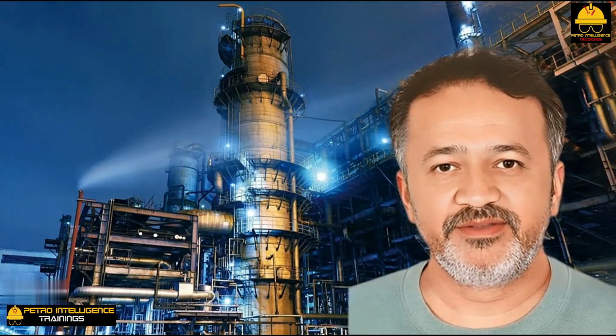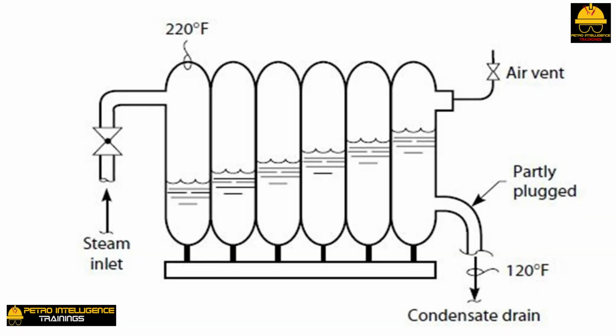Mechanics of subcooling. As the condensed steam flow out of the radiator is restricted, the surface area of the radiator available to cool the hot water increases. Hence, the water temperature leaving the radiator decreases. To summarize, the effect of restricting the condensate flow from a radiator or condenser is to build the water level in the radiator, reduce the rate of latent heat transfer from the steam, increase the rate of sensible heat transfer from the condensate, and reduce the overall heat transfer duty from the radiator.